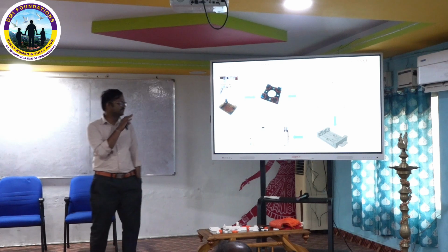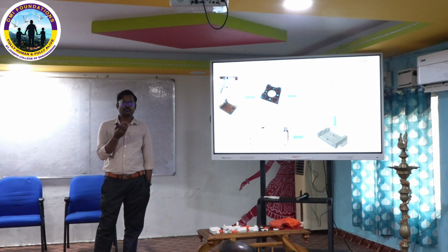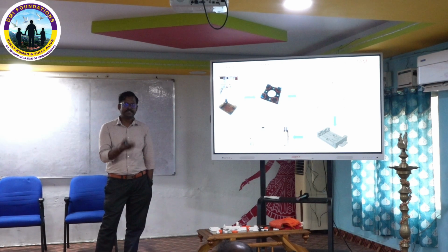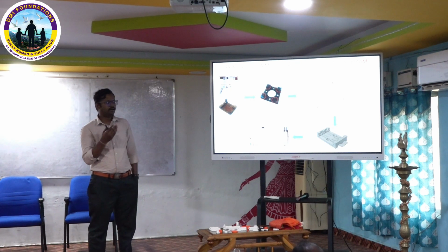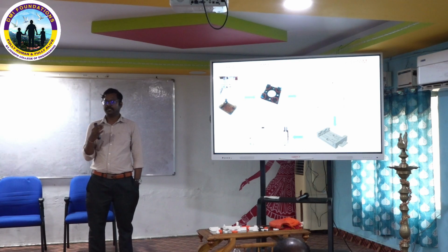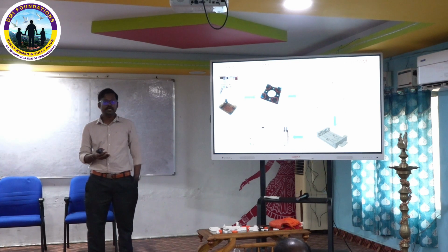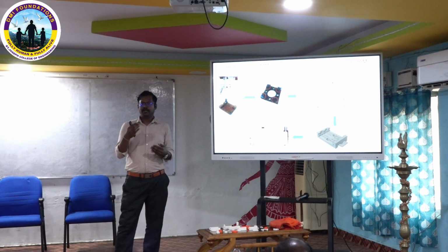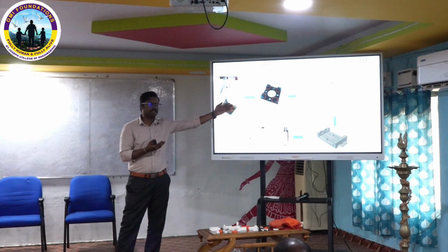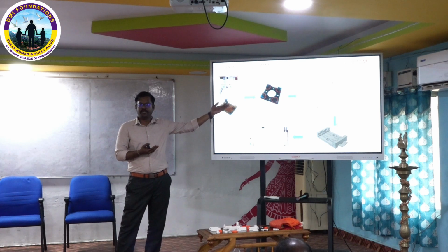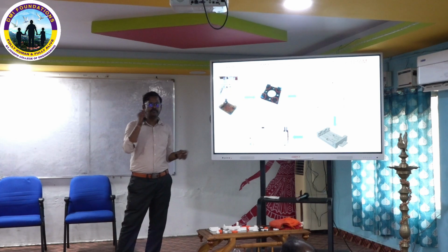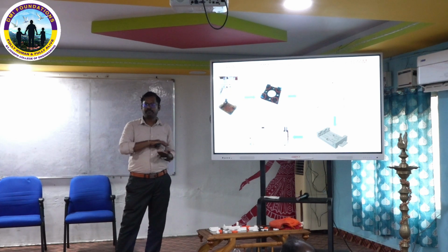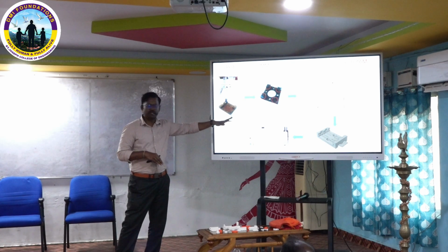In this work, this is a tool workpiece holder for ECM, electrochemical micro machining. Our senior researchers who did the work in ECM fabricated the tool workpiece with ABS or PLA material using additive manufacturing. They put glue on that, attach a magnet, and place the workpiece to hold it in the electrolyte bath.